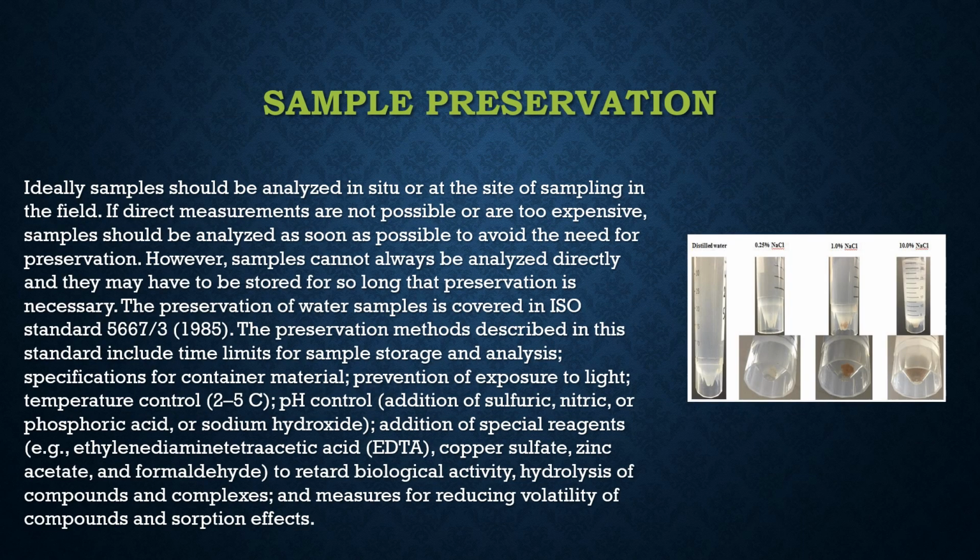Sample preservation. Ideally, samples should be analyzed in situ, or on the site of sampling in the field. If direct measurements are not possible or are too expensive, samples should be analyzed as soon as possible to avoid the need for preservation. However, samples cannot always be analyzed directly and may be stored for long periods, so preservation is necessary.